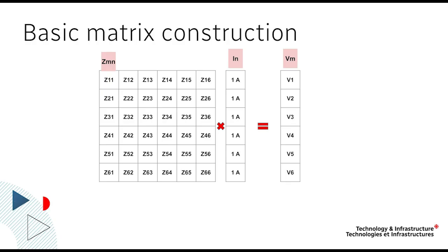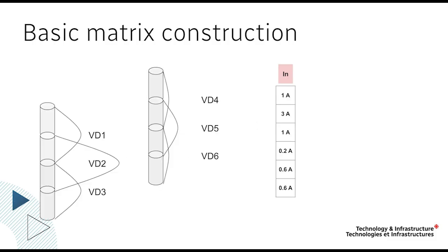No? Okay. So, once you have your impedance matrix and your excitation vector, you just need to solve your system to know what current would create the excitation vector based on the impedance matrix that you have. It's not high school, it's college-grade matrix resolution. You can choose whatever solver you want, like Gauss-Jordan or LU pivoting. So yeah, once you solve for the current by inverting the matrix, you get the solution.